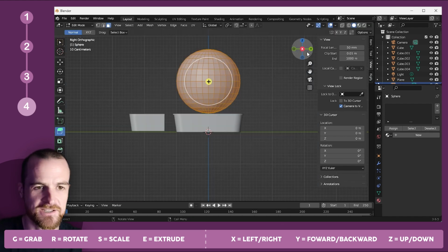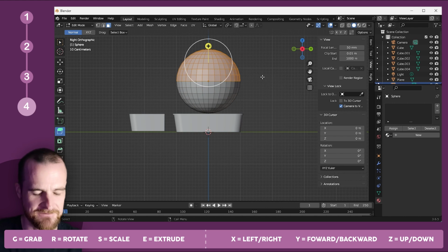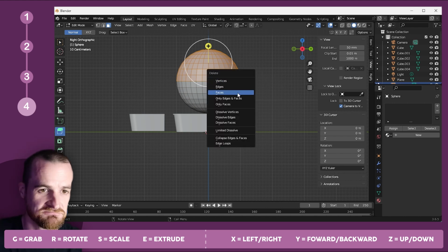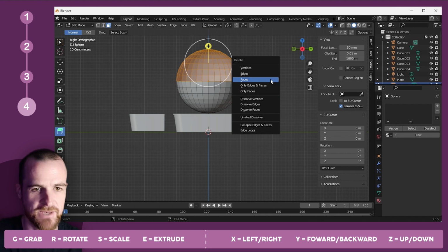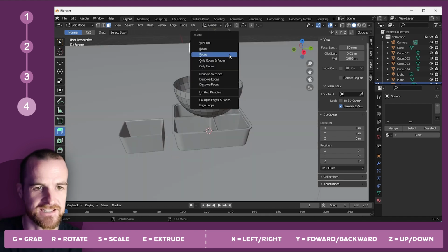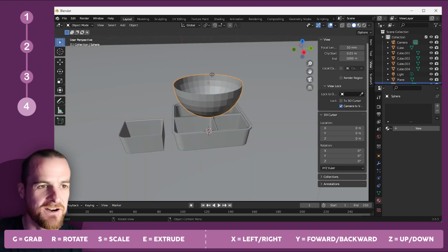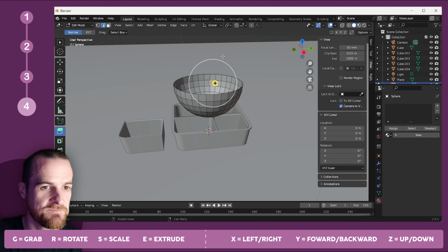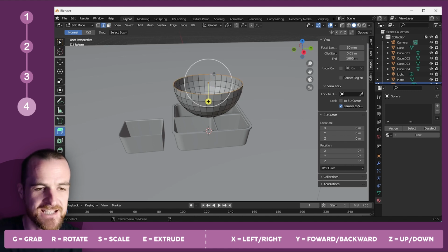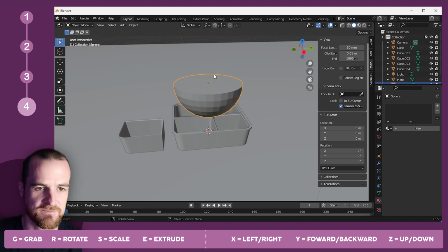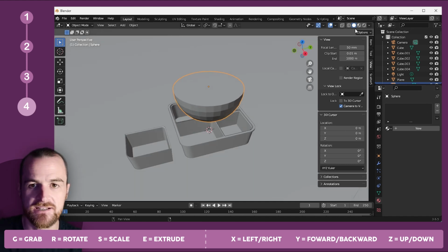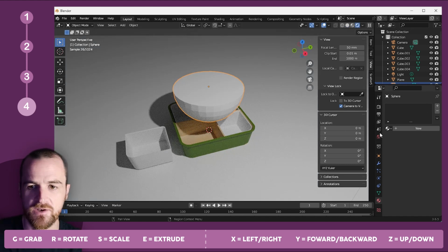And now you want to click on your little X button and we're just going to delete half of this UV sphere. So we want the tomatoes to obviously just be half. Select the back faces. Select that little guy there. And now, go into your tomato, hit the Alt button and select that whole rim and just hit that F button, sorry, F for fill.